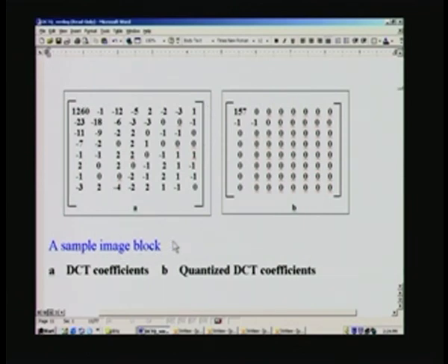The first coefficient will be 8 corresponding to this term, and 16 for this, then 16 for this, and another 16 for this, then 19 like that, it goes 22 and so on until I think 84 or some such thing. And you have to take one DCT and divide it by the corresponding coefficient.